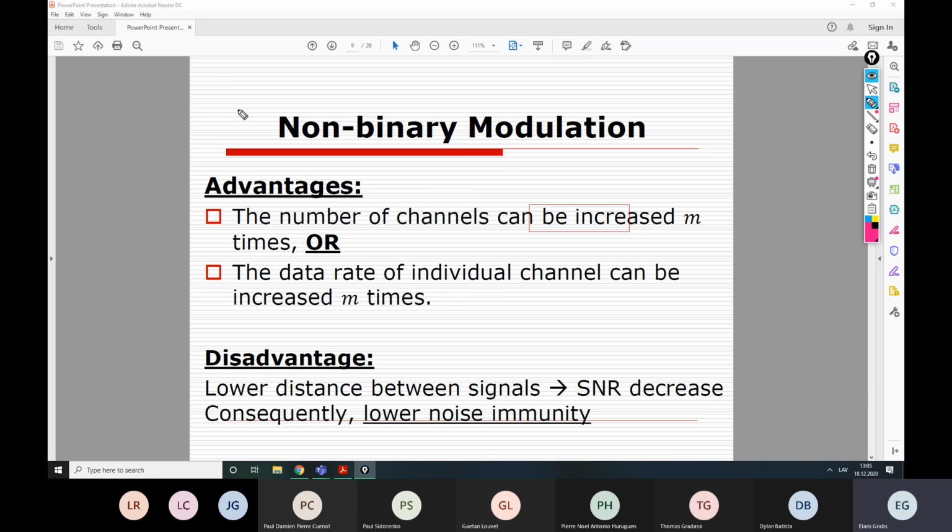However, for example, in a Wi-Fi system we actually have different modes. I think there were like 5 or 6 modes with different modulation types. Amongst them, we had binary phase shift keying as the most robust method, but also the slowest method, right? It works when you are quite far away from the access point, or there is a lot of interference and the signal is weak. We as users don't do that, but the Wi-Fi receiver itself sets the modulation type to this. Then it allows you, maybe not too fast, but anyway, to send and receive data without errors. Here we also have coding for error correction, right? Naturally, some errors happen and some of them can be corrected.